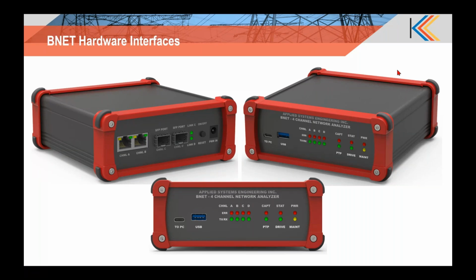I have one question that has come up. Can you simulate typical faults other than over and undercurrent and voltage? For example, simulate the SV streams needed to trigger a distance protection fault or differential protection fault, or under and over frequency. Right now we don't simulate the frequency, but that is one feature we could add. Definitely, that was a request we had from some other customers as well. We can add it into a roadmap, but right now we don't simulate complex protections.